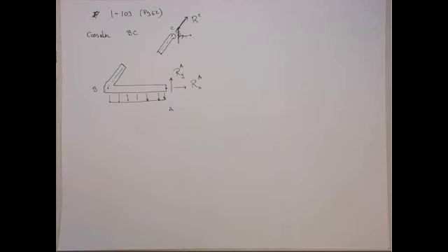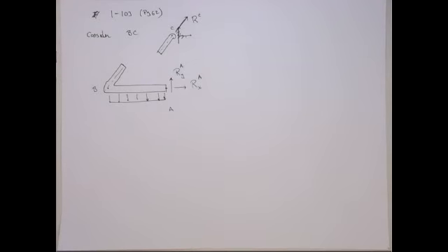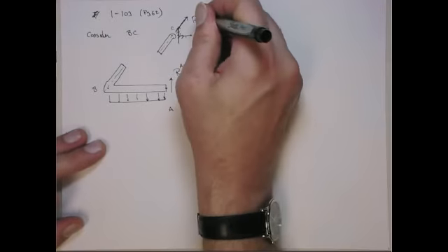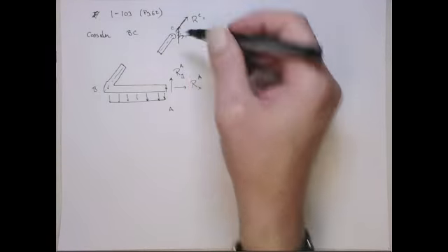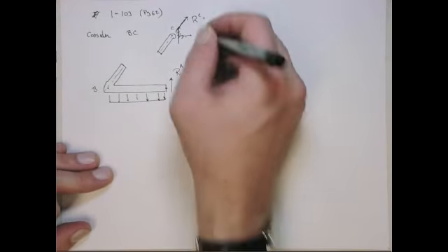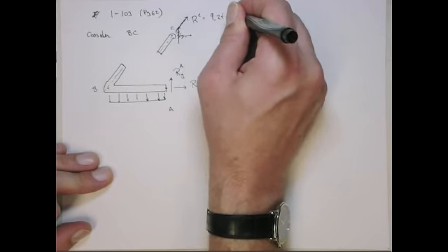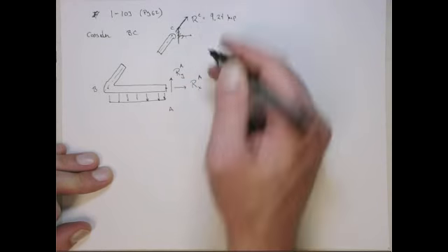All right, here we'll do the second part of problem 103. Last time we figured out the reaction forces at C and A. So just to put that in here, we know that the reaction force at C, we know the direction it acts because it's a 2-point element. That is 9.24 kip. It's positive, so it's acting in tension.